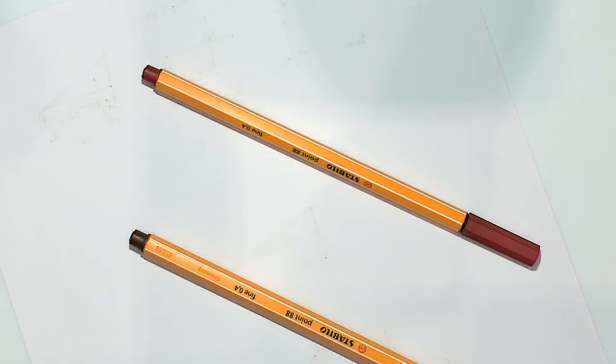The other question I had was for our structures course, we're doing capacity before. If we wanted to consider the self-weight on a free body diagram, we could just draw that as a load about its centre of gravity, and just treat it normally in the shear force diagram? Yeah, that's just a point. Or you could say distributed load, because the member is fairly prismatic. So wherever its center of gravity of that load would be, that's it. Or the bending moment could be changed. For example, bending moment due to point load and UDL are different.